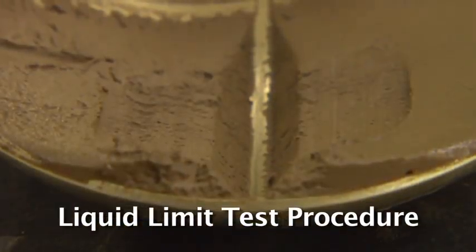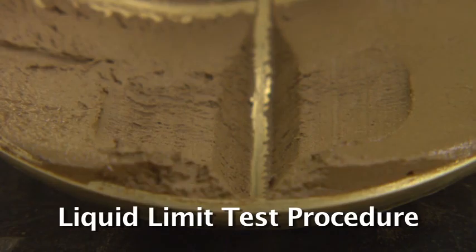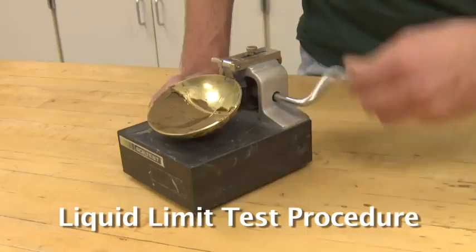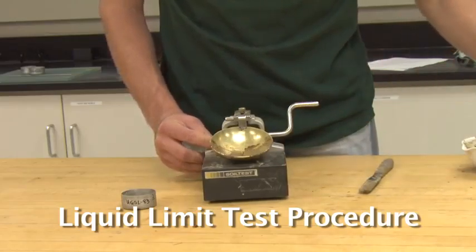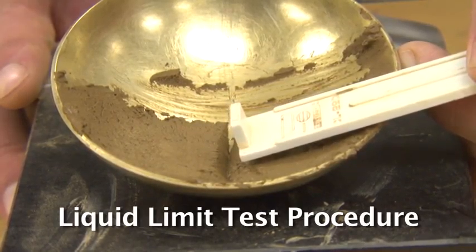If the shoulders do not contact the soil pat surface, too little soil has been placed in the cup and the test should be restarted. Once the groove has been made, rotate the handle at 120 revolutions per minute, 2 cycles per second, and count the number of blows it takes to close the groove in the soil pat 13 millimeters or 1/2 inch, which is the width of the grooving tool handle.